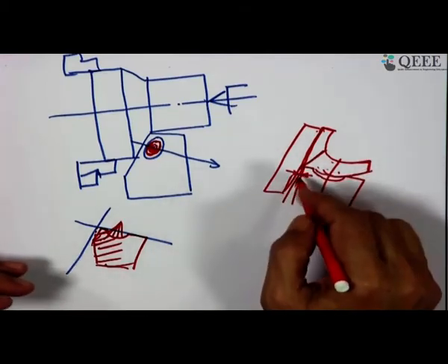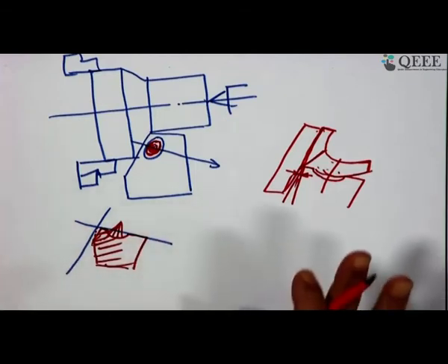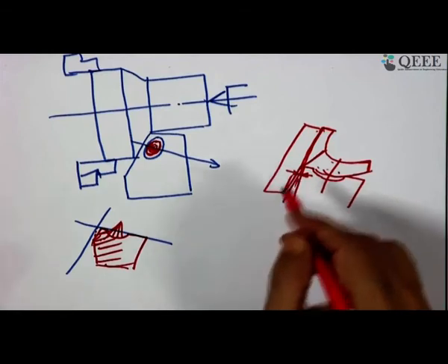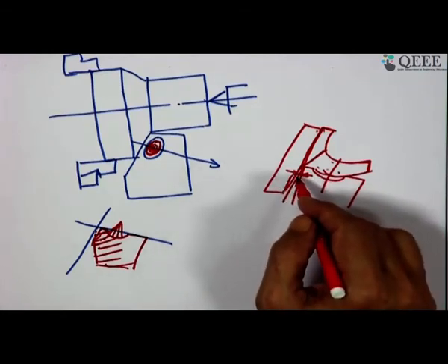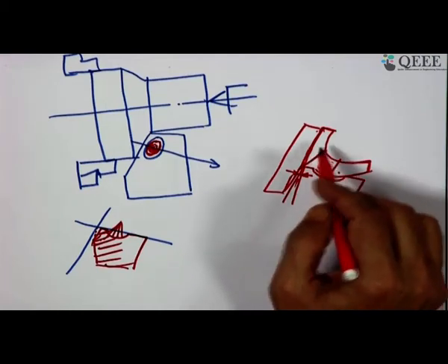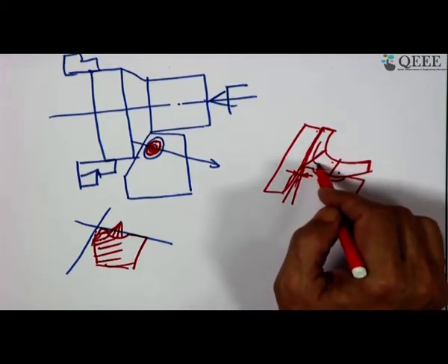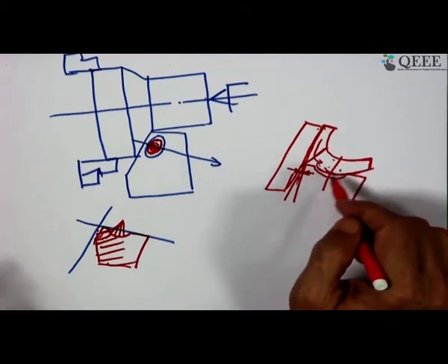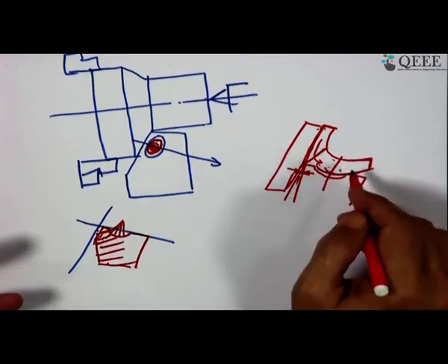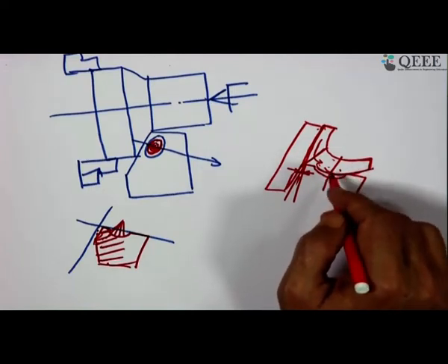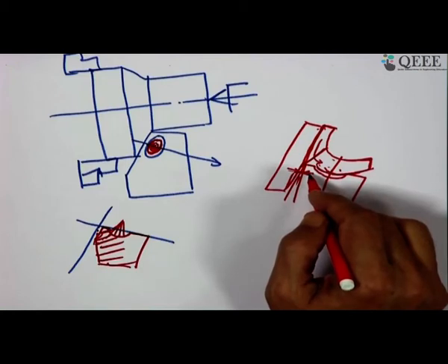So, mostly under normal conditions with the chosen speed, the nature of wear would be mostly abrasive in nature. But here, since the temperature is high, why is it high? Because the chip material goes through the primary shear zone followed by the secondary shear zone, it attains an addition of temperature, a twofold rise of temperature, and this temperature causes here wear which is known as temperature sensitive, and this wear is temperature insensitive.